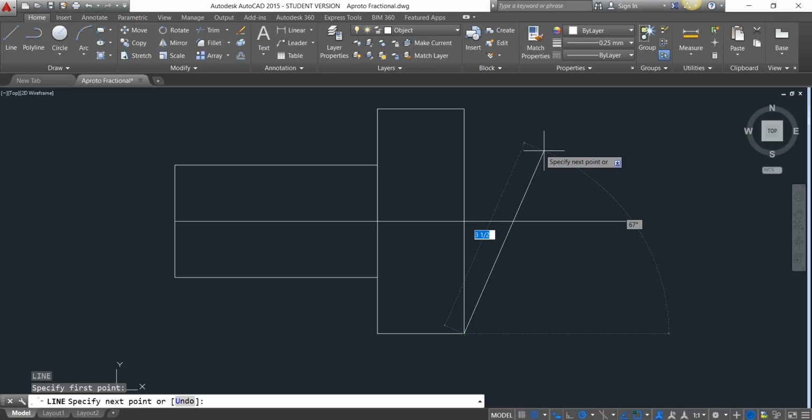The real trick here is selecting the correct angle. A lot of students would tell me that I would need to type in 30, but watch my cursor and watch if I go down to around where 30 degrees is. This should not look correct at all. So what students aren't realizing is that from here to here, this is 30 degrees. But look at where the angle is talking about. It's talking about from my cursor down, not from my cursor towards my vertical line that I've drawn.